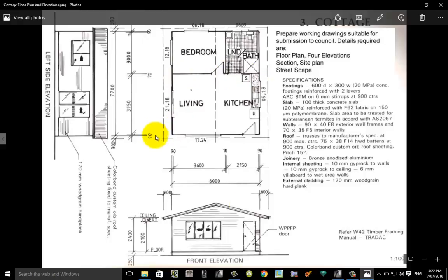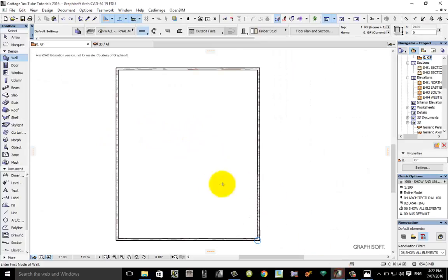So while I'm in wall insertion method, I'm going to hover my cursor over the internal corner of that wall. You notice when I do that, the computer puts a snap point in there, or a snap guideline, I think they call it. What that basically says is if I move my cursor away, you see that blue lines, could be arcs or straight lines, appear.